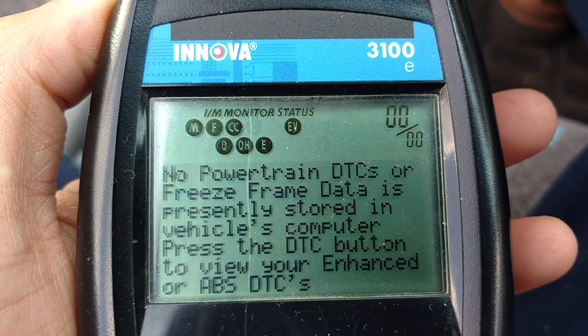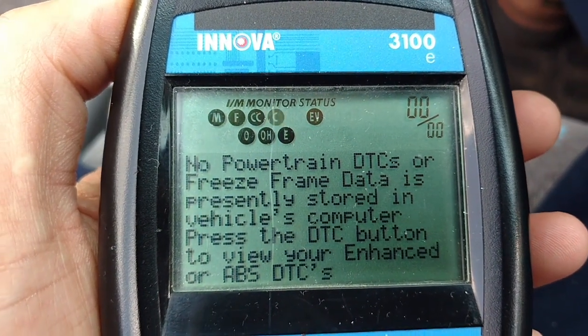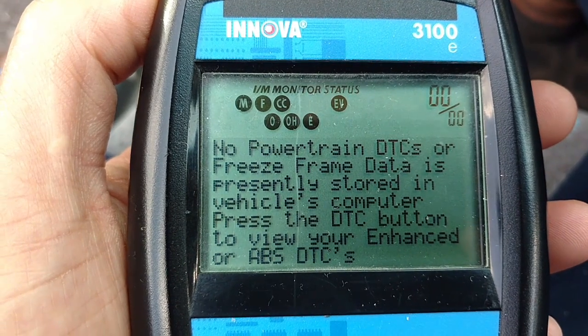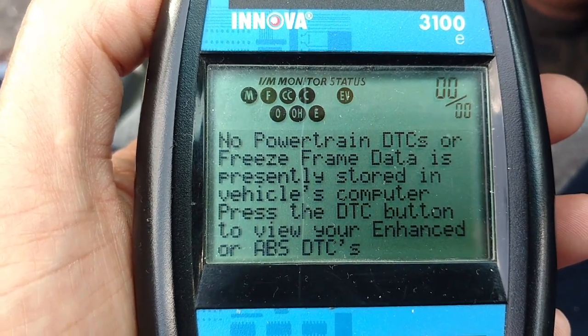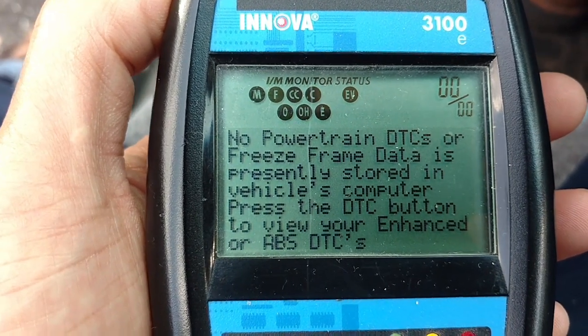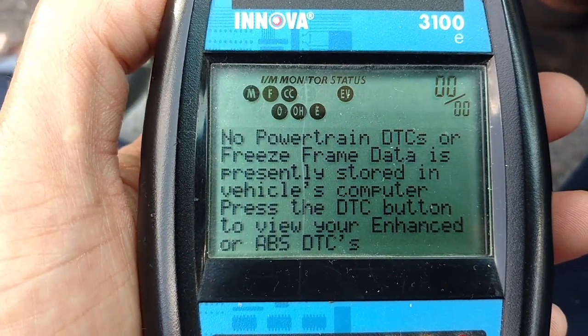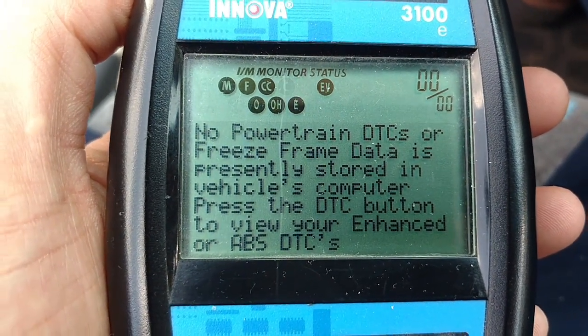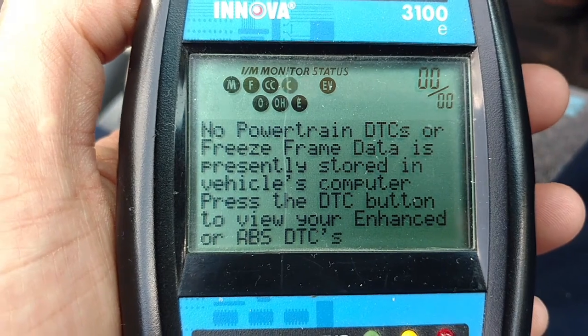Maybe my guess is, because I checked the air leaking, it was good. The VSV valve for the vapor pressure sensor was okay when I tested it.